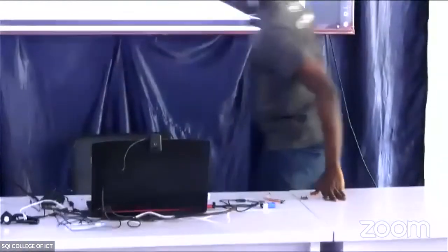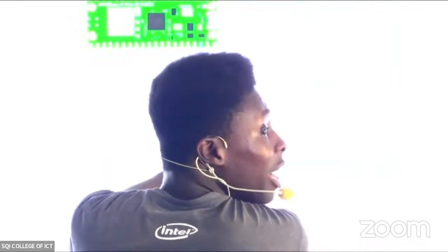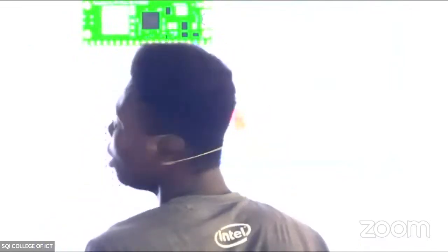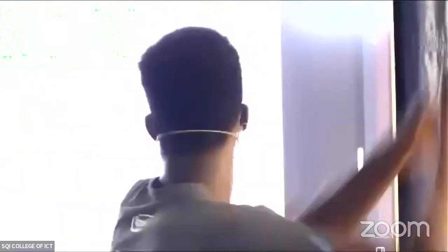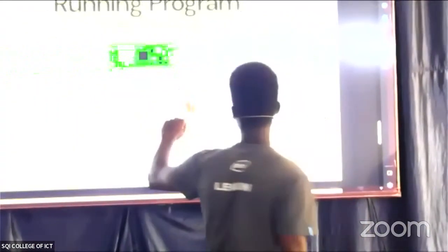Look up, everybody. This is where you connected your ground to, yes? For your second and third LEDs, you can tap ground from here to the ground of the other side. You can, if you connect a pin here, male to male wire, the wires that have 2 pins on the ends. If you connect it here, you can connect it to the ground of the second LED and the third LED. Do you understand? If this is one ground,